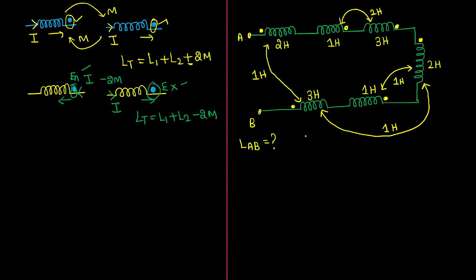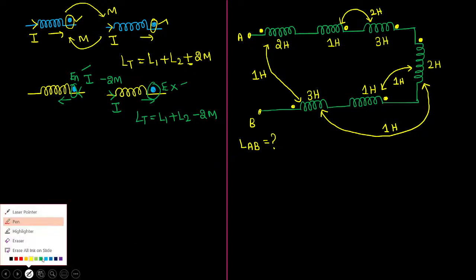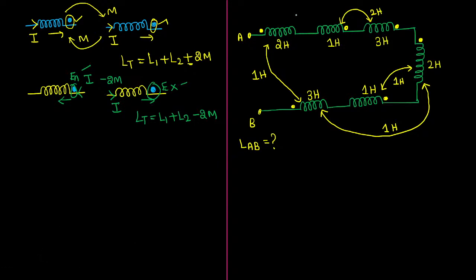This is very simple, yeah. How do I do it? What is very simple, sir? First of all, suppose in the examination, after giving this kind of circuit, you must observe carefully if the flux linking lines, these yellow lines, are not given between some coils. See, between this coil and this coil, is there any mutual inductance? No, it will be zero. Why, sir? They haven't given.